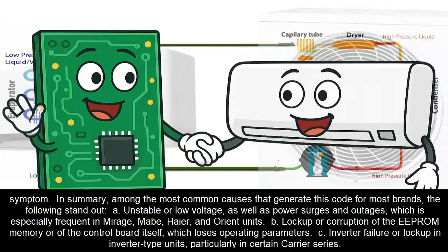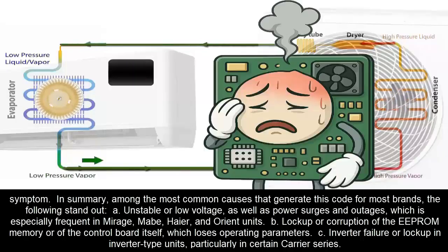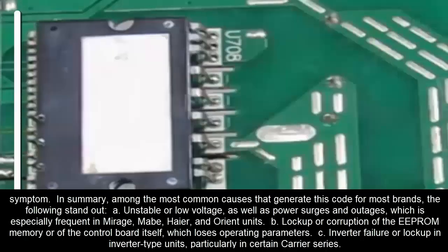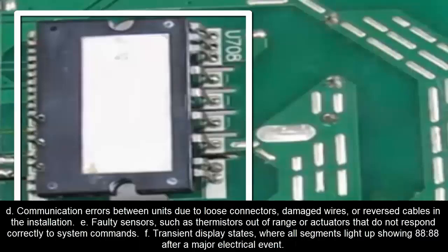Among the most common causes that generate this code for most brands, the following stand out. A. Unstable or low voltage as well as power surges and outages, which is especially frequent in Mirage, Mabe, Haier, and Orient units. B. Lockup or corruption of the EEPROM memory or of the control board itself that loses operating parameters. C. Inverter failure or lockup in inverter-type units, particularly in certain Carrier series.